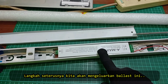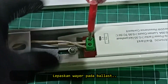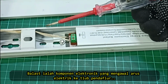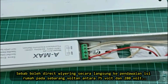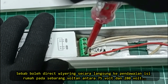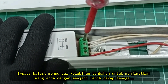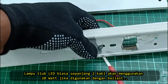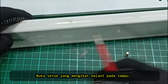Let's get started on removing the ballast. Release all the wires on the ballast. The ballast is an electronic component that regulates the electrical current in fluorescent tubes. LED tube lights do not require a ballast, since they can be powered directly by household wiring on any voltage between 75 volt and 280 volt. Bypassing the ballast has the added advantage of saving you money by being more energy efficient. A typical 2-foot-long LED tube light will consume 20 watt if used with a ballast, but only 14 watt if the ballast is bypassed. Unscrew the mounting screw that holds the ballast in place.